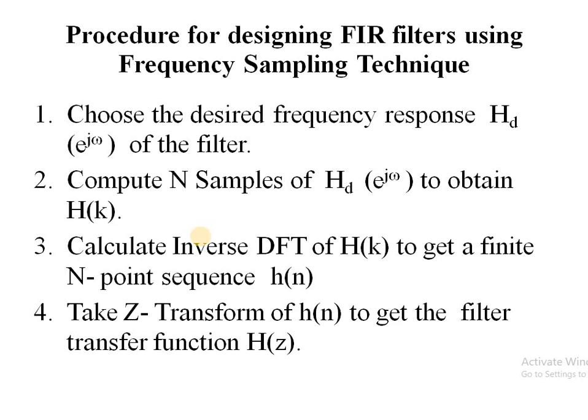The DFT of the impulse response is generally represented as capital H of k, and for practical realizability, the samples of this impulse response should always be real. But this can happen only if all the complex terms appear in complex conjugate pairs. It can be observed that the complex DFT coefficients exist only as conjugate pairs, and this suggests that the terms of H of k can be matched by comparing the exponentials. The term H of k e power j2 pi nk by N should be matched by the term that has e power minus j2 pi nk by N as a factor.